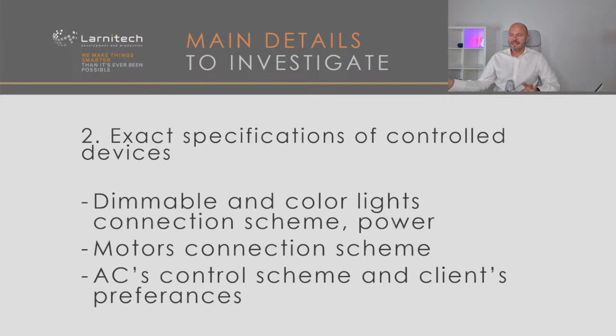And then exact specifications of all control devices. Sometimes we think that this is light, okay, and 5 of them we will just have on off, and 3 of them we will dim, and that's it, forget. Go to next challenge. And this is not working like this. If you dim something, you need to understand the power. You need to understand whether it's dimmable or not, what do they really install there.